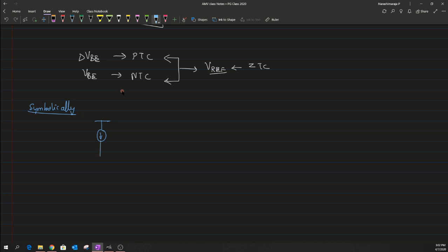a current source, and that is being passed on to a diode connected configuration, and this diode connected configuration will just create a VBE. Okay. So the one that I am trying to draw actually generates a VBE, or in short it is my negative temperature coefficient term, okay, for a given current, which let us assume that it is equal to I naught.